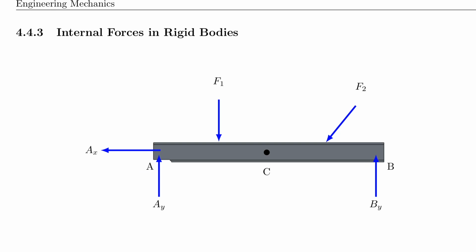And you will have to continue to do that for each upcoming problem now. This is really the first thing you have to do, and that's why it's so important that you're so proficient at finding support reactions, because the support reactions define the internal forces. And if you do not get the support reactions correctly, then you cannot find the internal forces correctly, in this case at location C. So what do you do after you have the support reactions?